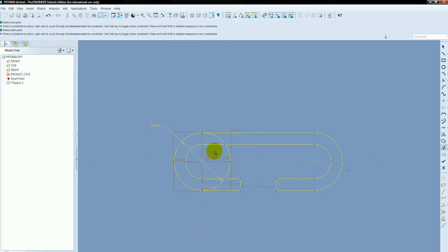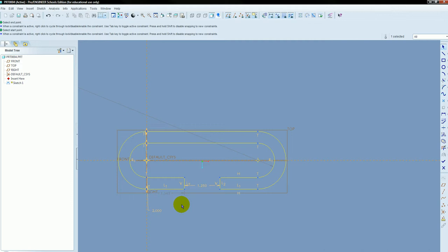And then it's going to be the same trimming on this side, so that what I'm effectively left with is that overall shape. And everything should be tangential. For the most part, most of this stuff is going to have the proper dimensions on it already because of the dimensions that I've already placed. So what I want to do now is I want to change this dimension to 1.25, because that's ultimately what that's going to be.